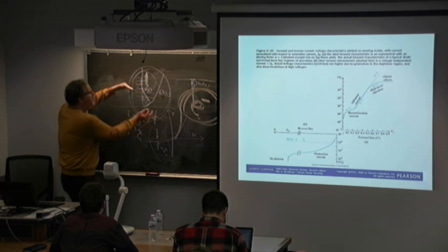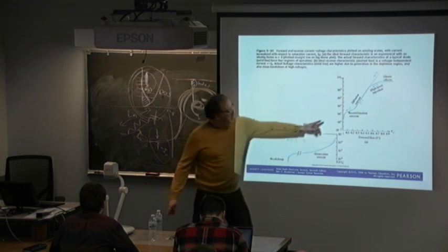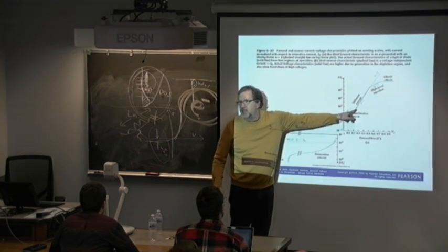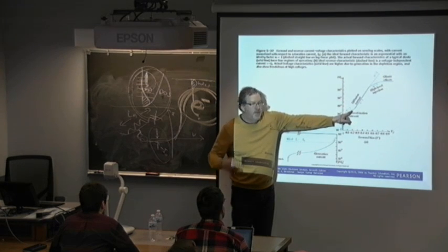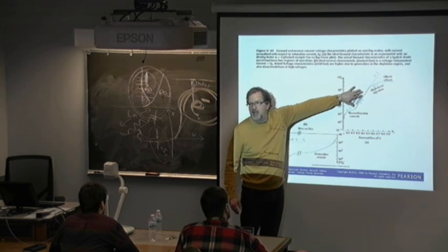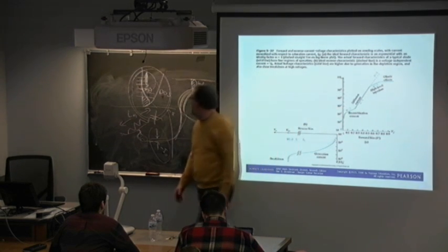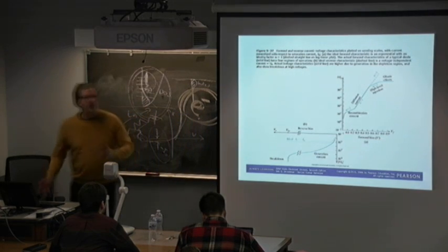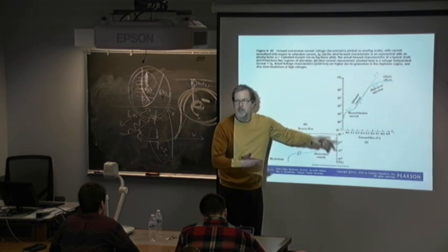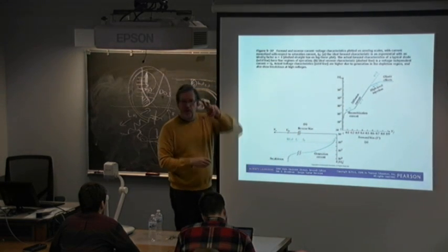Because this is lifting this up, and so until you get to the cut-in voltage, which you learned in silicon circuits is 0.7 volts, the diffusion current hasn't really kicked in. That's what normally happens. That's the ideal case. So before the diffusion current kicks in, you simply have generation recombination, which is a two-carrier event. Generation recombination has an electron recombining with the holes, two carriers.